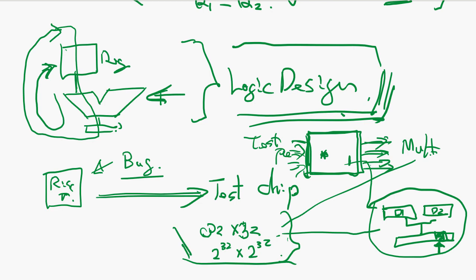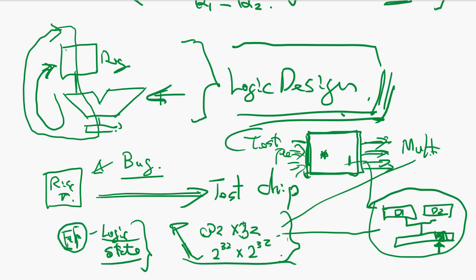And this kind of testing is another challenge, especially when you have a lot of flip-flops inside the chip. Flip-flop logic state cannot change so easily. It's a very complex condition for the logic to change. So you don't know if this particular flip-flop is working or not by generating a test pattern and running it through this chip.